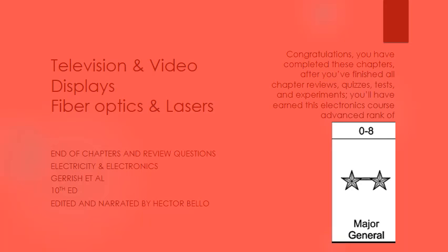Next, a microchannel plate, or MCP, multiplies the electrons. Then the electronic focus manipulates the beam of electrons toward an eyepiece, or charge coupled device, CCD. The electrons strike the phosphor screen, releasing light energy. The light energy can be viewed directly through the eyepiece or on a digital display unit.